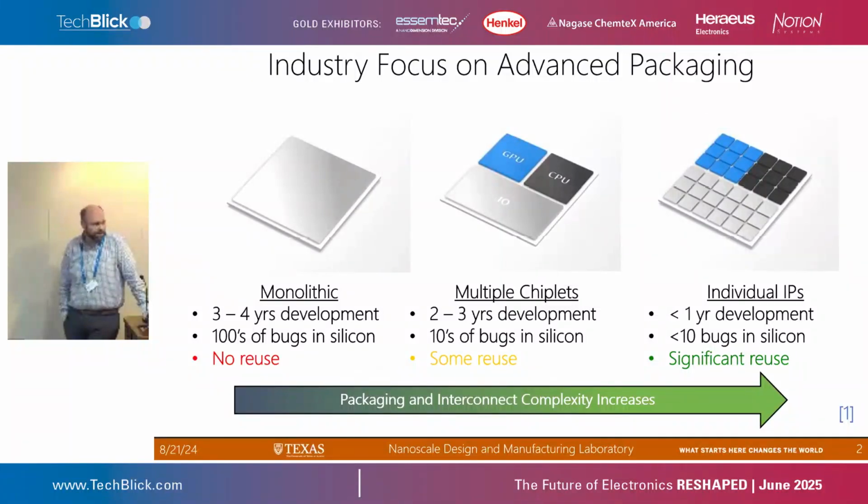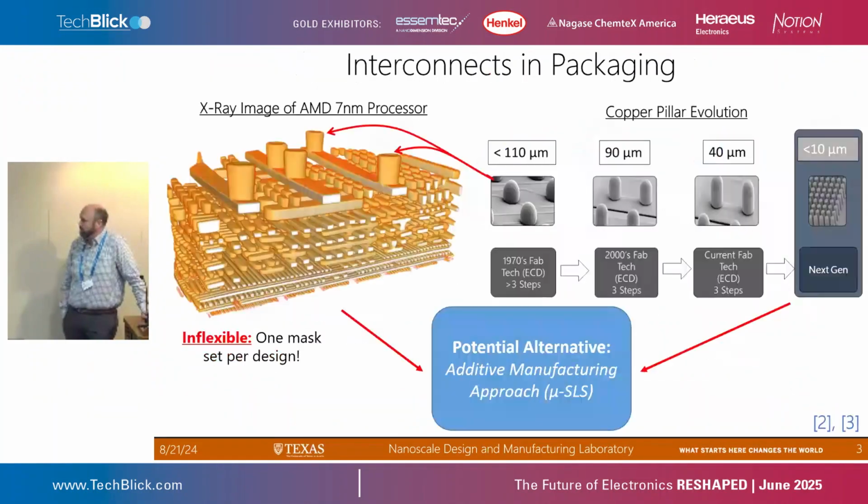We want to be able to rapidly swap out different chiplets in a structure in order to make development times lower, but also, as you get to finer resolutions on some of these chips, yields go down as you make big ones. And you can increase functionality by having multiple types of chiplets in a package. That's really the thing that we've been looking at.